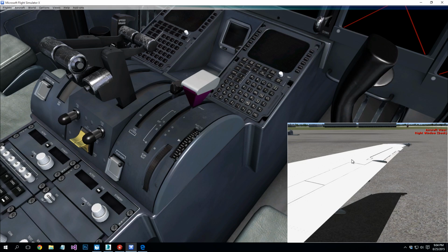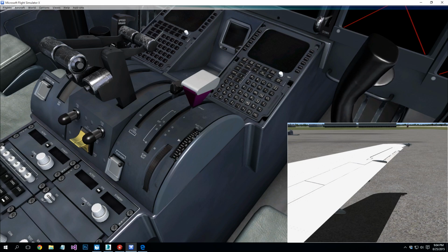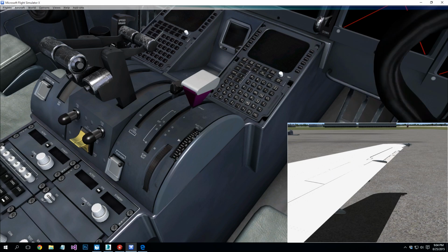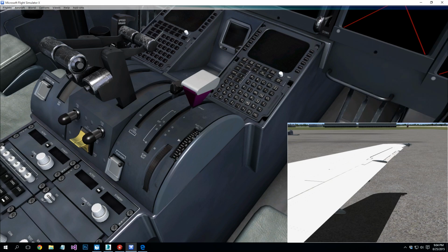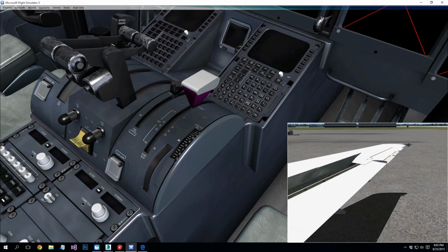Well, the other interesting thing about the 717 is that its ailerons and elevators are actually aerodynamically positioned, which means without airflow, the ailerons themselves will not move. Only the tab on the tip of the wing there will. That deflects airflow and will push the elevator. We've got that simulated here where without air we can't move it. You do see the spoileron moving around as we're deflecting.